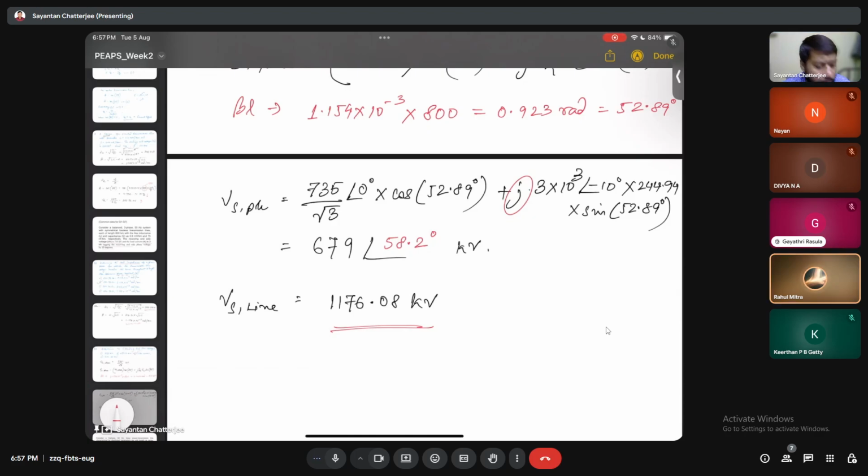So that last part, can you repeat? That reactive power flows from higher magnitude to lower magnitude, or what was that you mentioned? It is just a convention. Means if you do the mathematics part, you can generally observe. It's a generic convention that active power flows from the higher phase angle to lower phase angle, and reactive power flows from higher voltage magnitude to lower voltage magnitude.